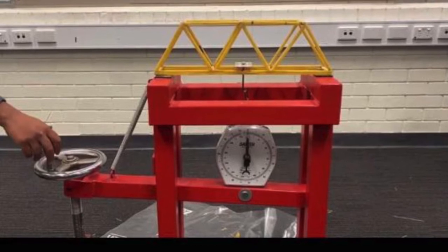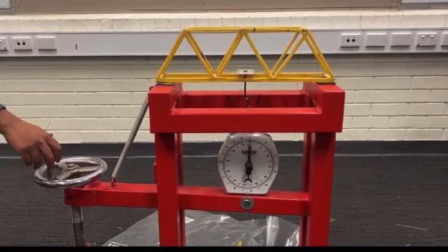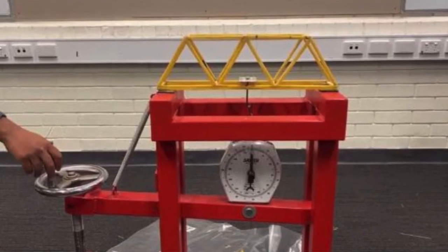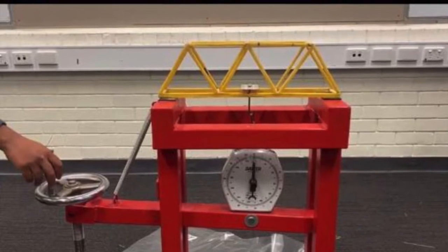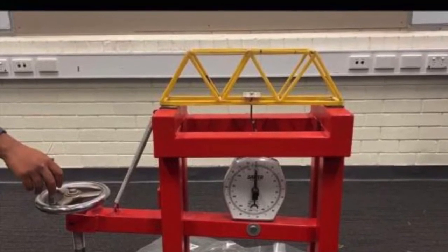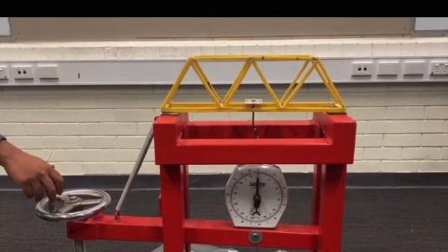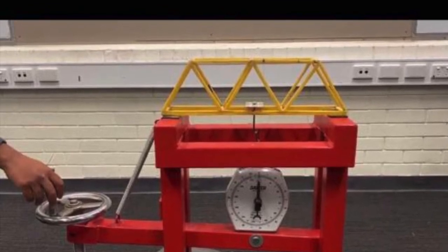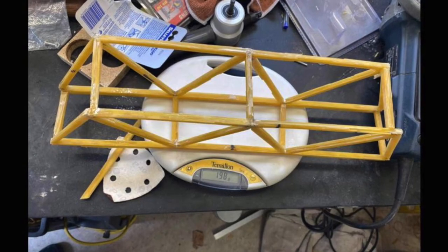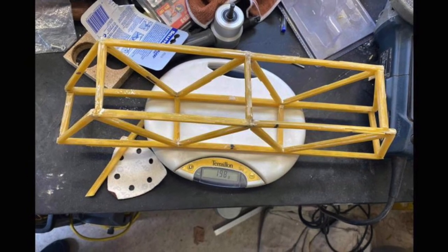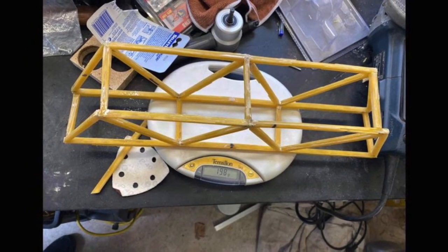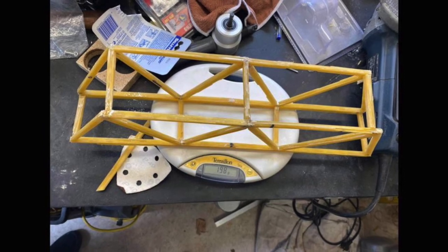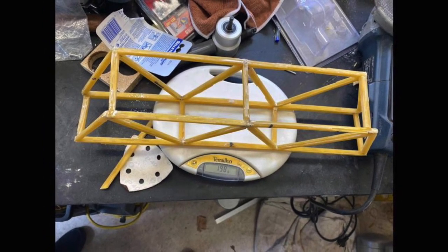For our final design, we made it 450mm long, giving us ample room to span across the full area. It was 80mm wide and 150mm tall. This change in the design gave us less weight to use on the I-beams, as we needed more trusses and other beams. This bridge was sturdy and weighed a perfect 200 grams. It managed a weight of 14.5 kilograms.